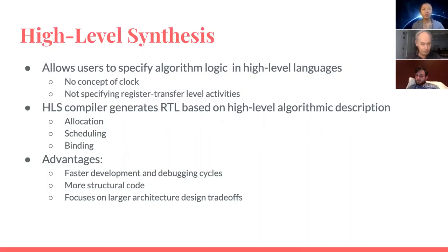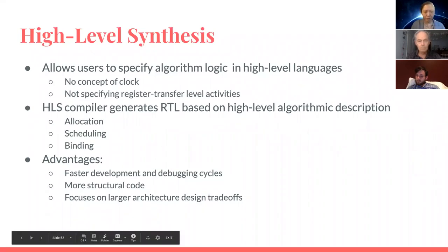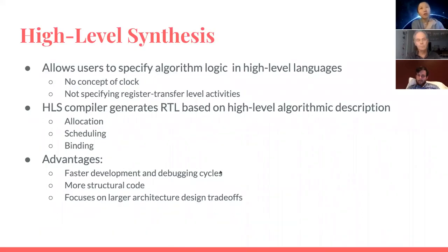And then this high-level synthesis can help us, one, to map very high-level abstractions onto low-level logic. Secondly, it helps us to easily specify the interface connections, which I'll mention later. And lastly, it allows people to explore more architecture design questions rather than specifying cycle-to-cycle operations. It automatically helps people to pipeline the design so that you don't have to do a lot of retiming yourself, like moving registers around and messing up your design. It can help you optimize for the clock that you're aiming for by automatically inserting certain pipeline registers in your algorithm.